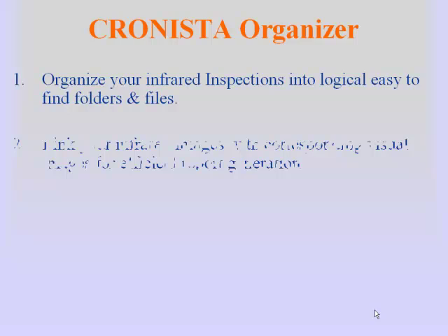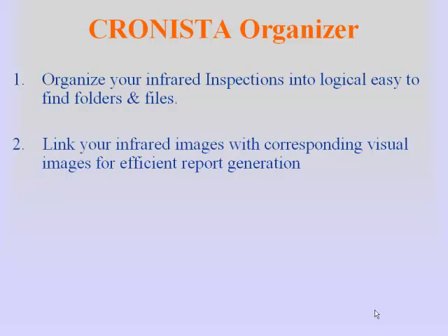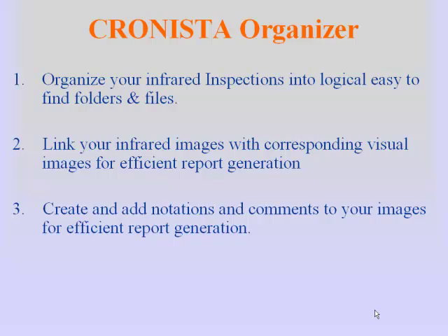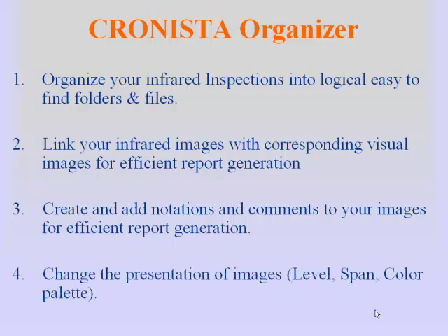Cronista allows you to organize your images and inspections into logical folders and files and transfer images from one to another. It allows you to link your digital images with your infrared images to be used in your report by using the drag and drop function. You can create and save notations and comments to your images for efficient report generation. You can also change the presentation of your images using the level and span and color palette functions.